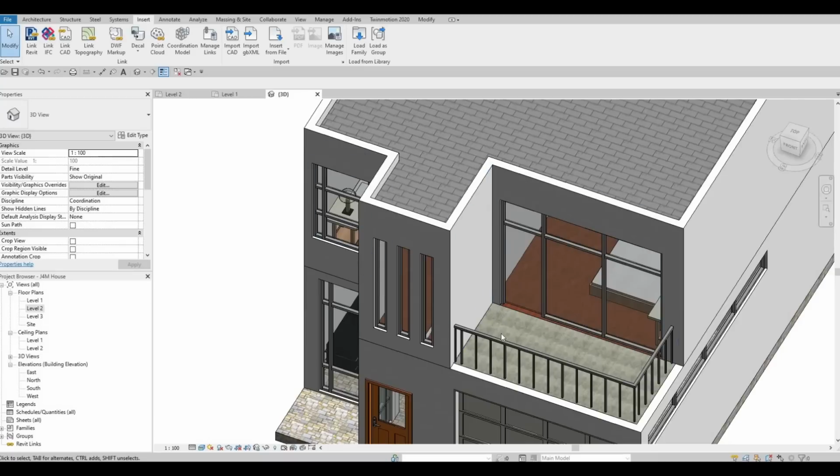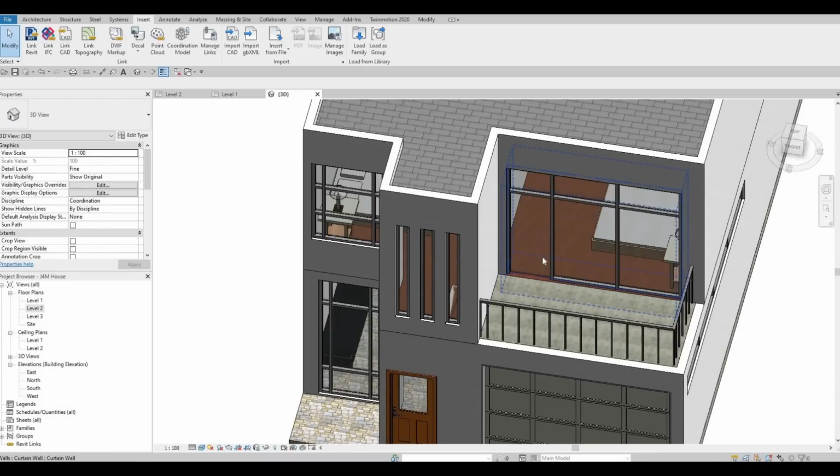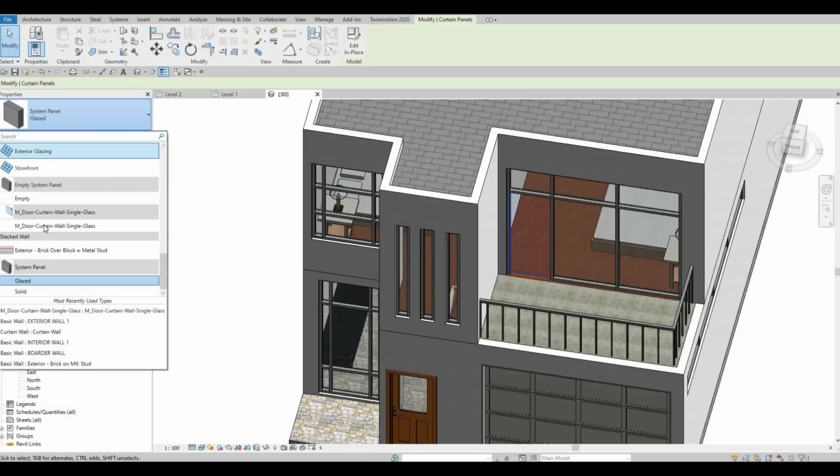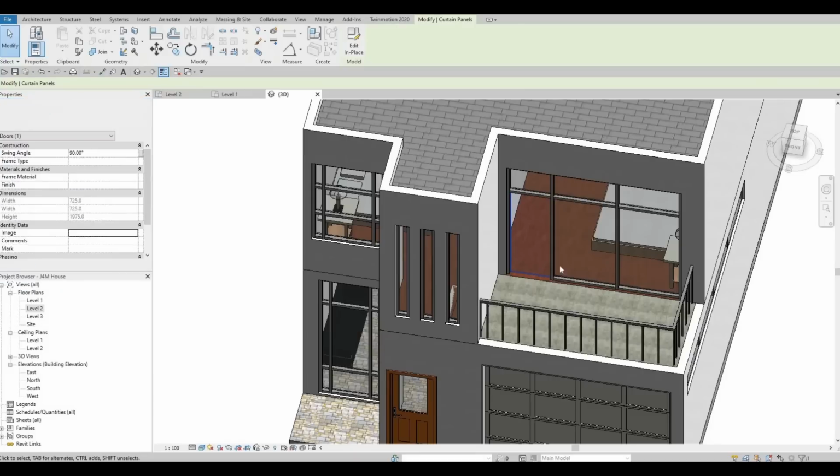And then now what you need to do is you need to select the panel, but at the moment if we go to our mouse pointer, it's selecting everything. The trick is to click on tab and then it's circle around. It will go and choose the panel. Once it chose just the panel, you need to select that panel, and once you select that, the property will appear here, and you could just now change it to the door that we want.